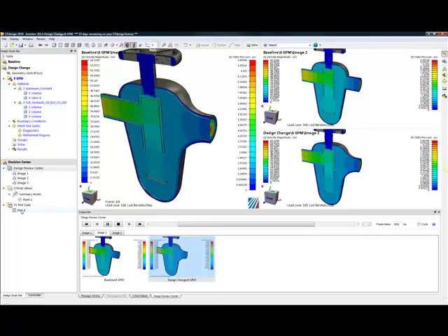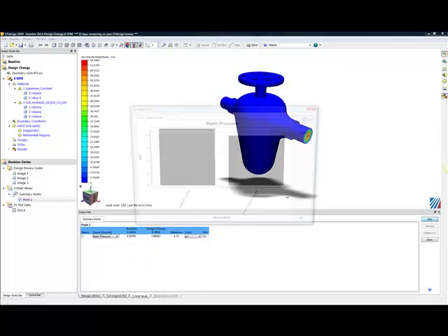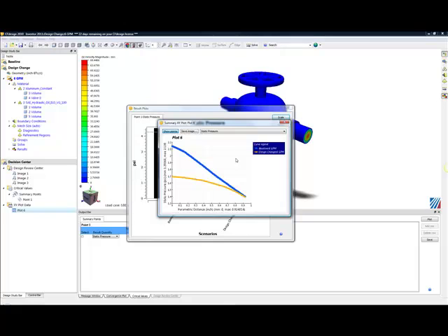Keeping in mind that critical value that I had previously, I can now use that 4.25 and plot that across both of my designs. And clearly my new design passes. Next, I can use the XY plot to understand the pressure drop through the valve. All while leveraging CFdesign 2010's multi-scenario design study, cloning, and Inventor 2011's connection to Autodesk Fusion.